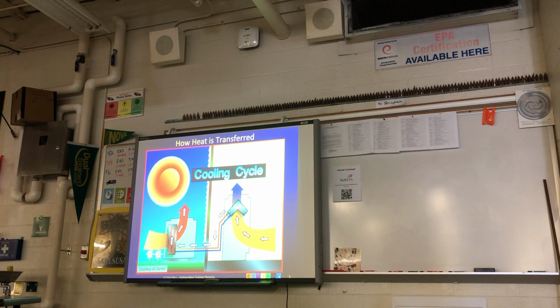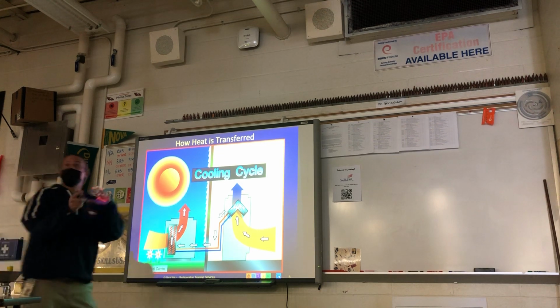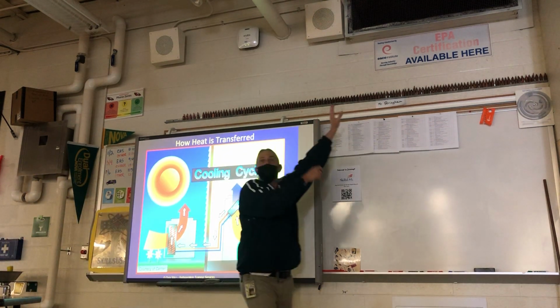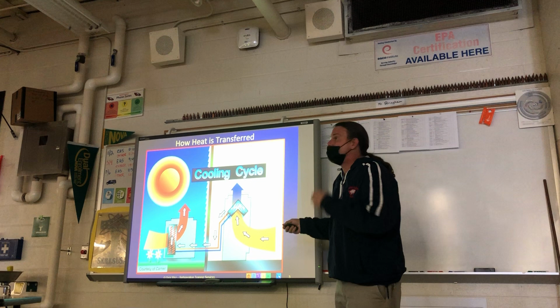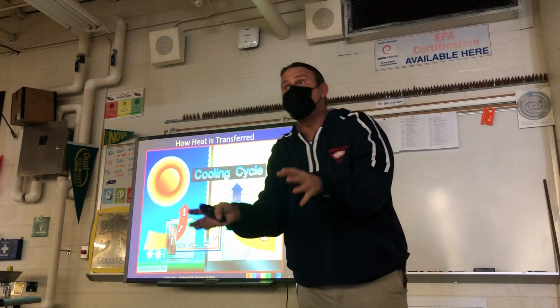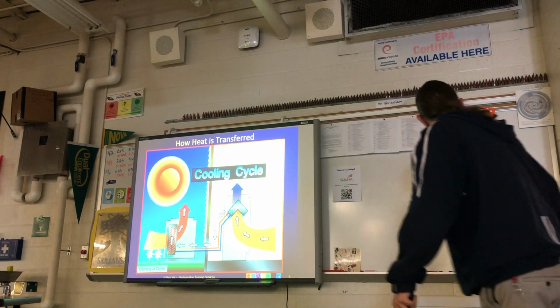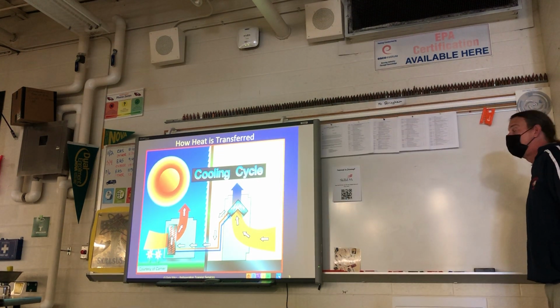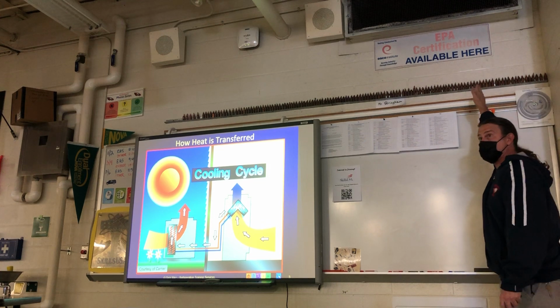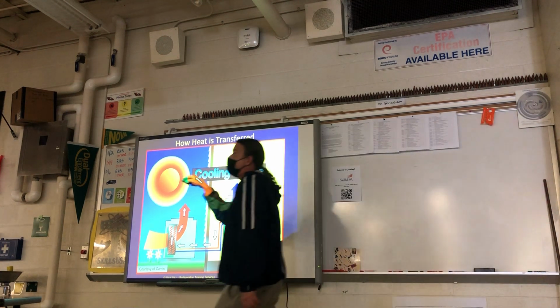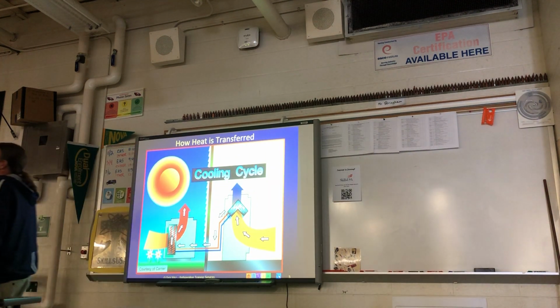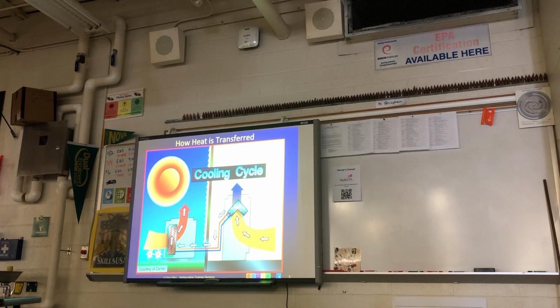All right, but you get it now, right? So here, this should be about a 20-degree difference. If I've got the AC on, and you're starting to feel warm in here and want to know if the unit's on, you turn the thermostat down to cool, and we're sucking in 75 degrees here. That means over here, if the AC's running and everything's normal, it should be blowing out about 18 to 20 degrees colder. So what would that be? 75 minus 20 is 55. 55 degrees blowing out of here.